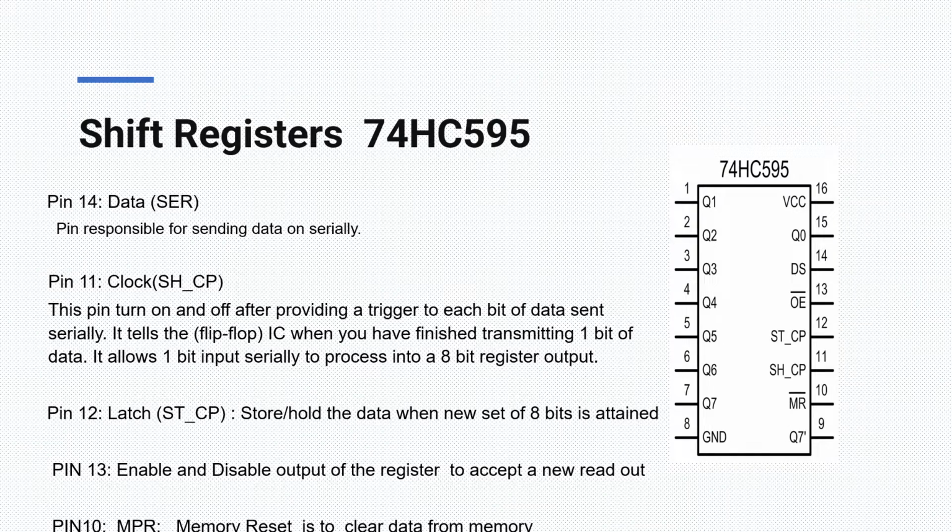Alright guys, so we're gonna explain shift register 74HC595. The first pin on this register is pin 14. Pin 14 is responsible for sending the data serially. And we're gonna look at the following pin, which is pin 11, which is a clock pin.